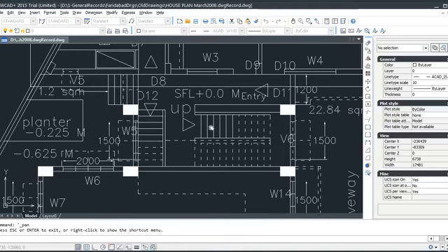Risers should be of equal size. All risers must be equal height, and all treads must be equal. Landing is different, this is important. You have to select the height of the floor depending on the riser. Don't take the direct height, saying I have to take so many meters, because then your riser will be in decimals, and that's no good. So either fix 150 mm, or 125 mm, or 100 mm.